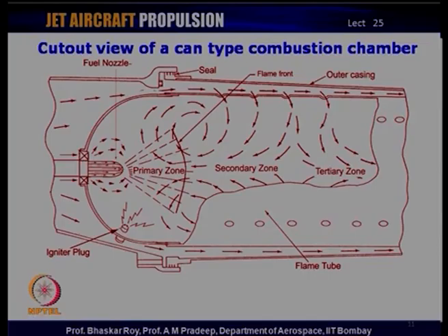The injector that you see here, and we will be discussing the injection process later on, maybe in the next lecture, actually ensures that you have sufficient injection of fuel for the corresponding operating point of the engine, and that is done by the engine control system. So, these are the various operating conditions of the combustion chamber that ensure that you have a continuous combustion, you have a controlled combustion, and you have complete combustion given the shape, the size and the space that is allotted to the combustion chamber.